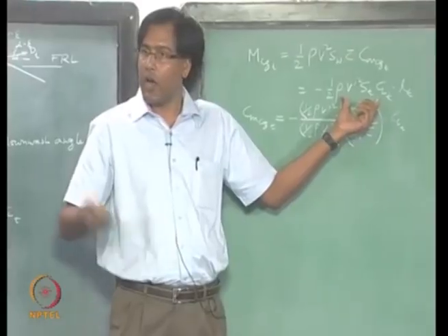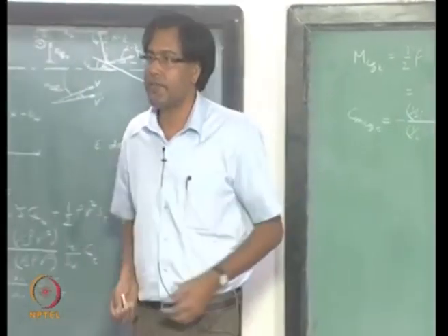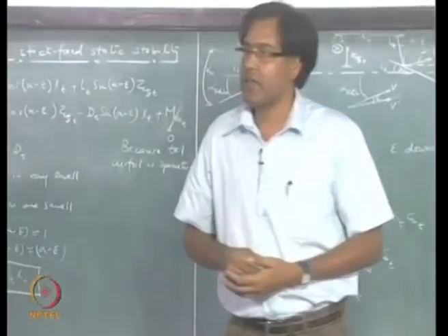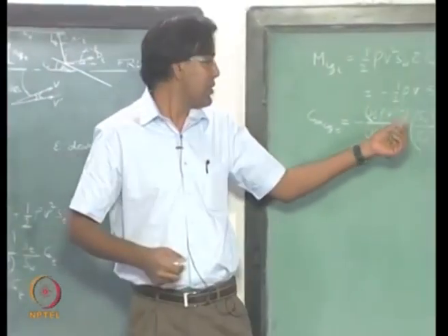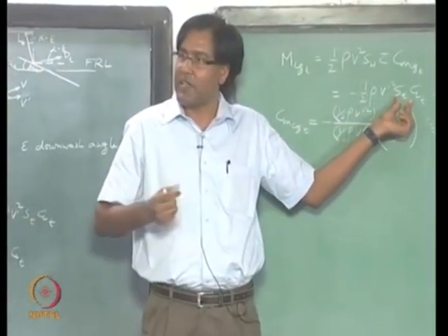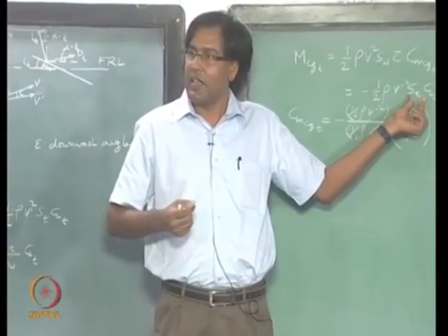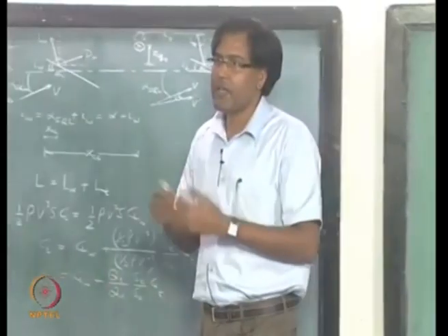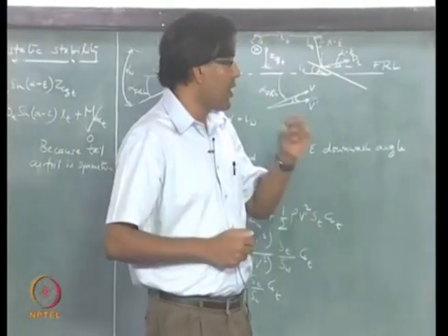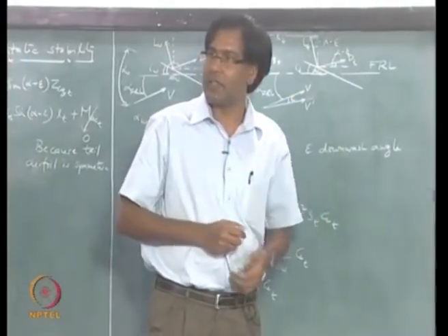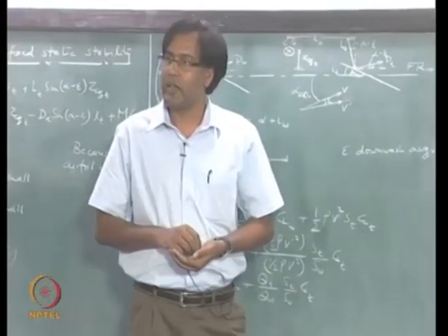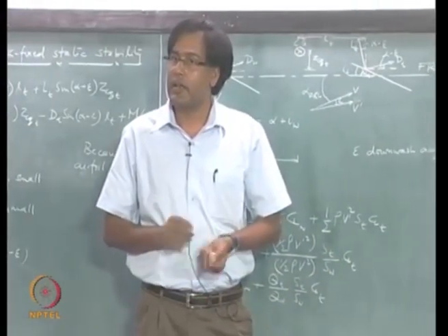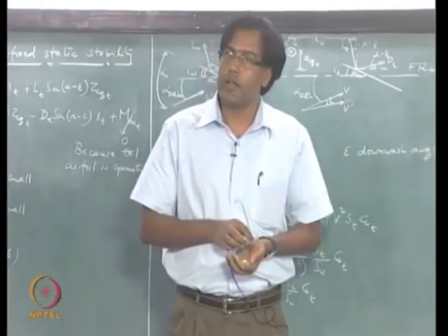Yes, so it comes. So, how do you calculate lift over any surface? You have to take the area of that particular surface, right? But why are we using SW for this? I am using it only for non-dimensionalizing the quantities. Why not? We have been using SW so far. We use whatever consistency uses.